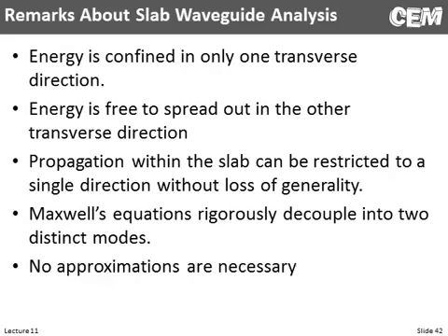Another bullet that you need to come away with here is that Maxwell's equations decoupled into 2 modes. This happened when we did the quasi-analysis, but we used an approximation to split them there. Here they rigorously decouple into 2 distinct modes. So in slab waveguides, there actually are two modes. Channel waveguides, we artificially did that. And so we really didn't make any approximations. What we did is we looked at the geometry of our guide, and that let us simplify Maxwell's equations.